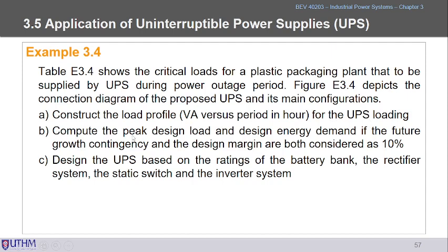For task number 2, we need to compute the peak design loads and the design energy demands, if the future growth, contingency, and design margin are all considered as 10%. Then finally, we need to design the UPS based on the ratings of the battery bank, the rectifier system, as well as the static switch and the inverter system.